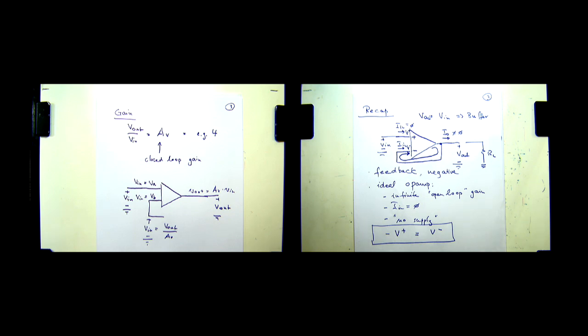Okay, so apparently that's the thing. Now we just need a way to tell the op-amp that we want this voltage to be a fourth of V out. Do you know of a circuit that can take V out and produce 1/4 of V out? A voltage divider. Hey, you know, these things are useful, not just for the exam. They're truly useful as circuits.